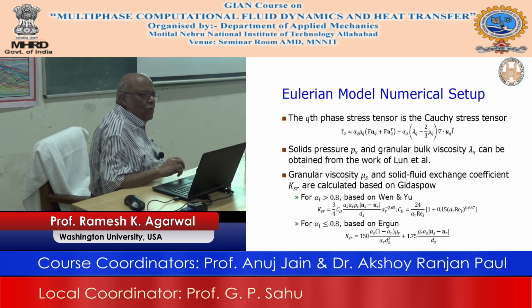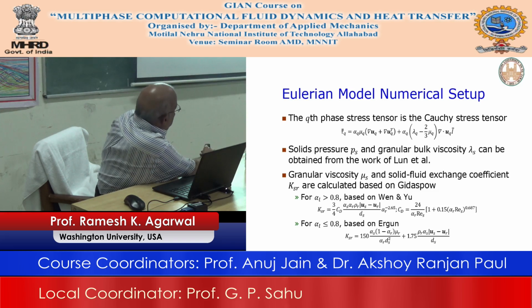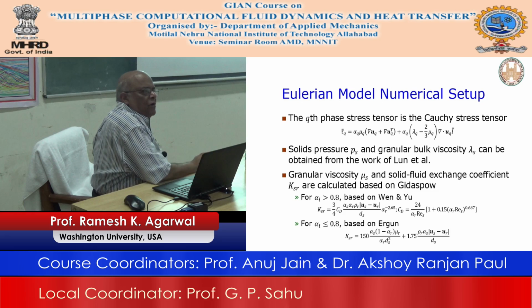You can't change the equation, right? They have been there since 1845. So the equations are the same, and they are being applied to two phases. If you consider both phases as fluid, then it's a two-fluid model, Eulerian. If you consider it as a DEM, where is the difference? The difference is this term. The modeling of this term in Eulerian versus DEM becomes different.